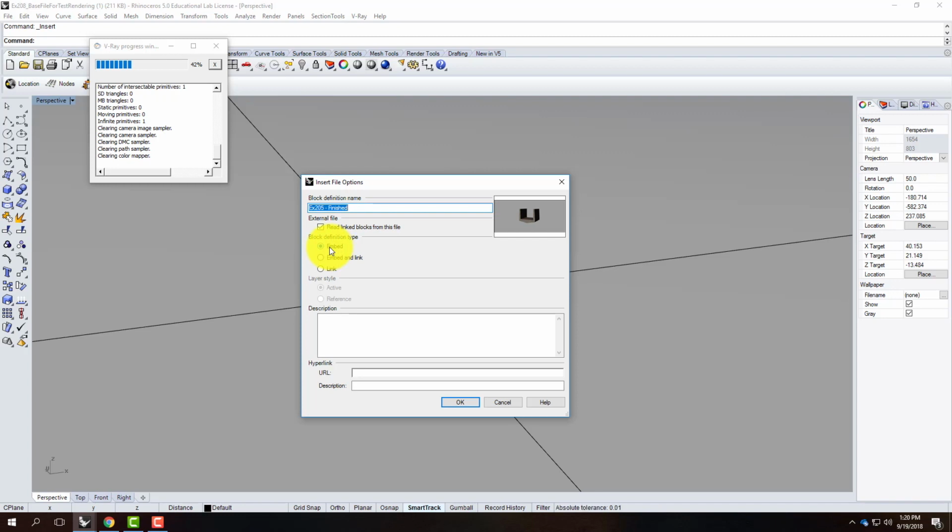But it also makes our files really large in size. Long term, this file doesn't matter, but imagine you're in the 221 skyscraper studio and you decide to throw some windows in, and suddenly you have 2,000 windows. Having them linked as references is a lot better than having them embedded in your Rhino file. So these blocks are really going to make a big difference.